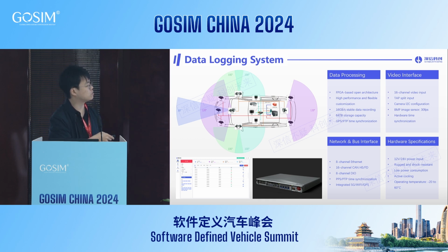For example, you need to trigger your cameras by aligning the camera exposure time with the LiDAR. The LiDAR is scanning in a rotating pattern, and once it reaches the view of any one of these cameras, you want that camera to expose and take a shot at the same time. So a very accurate timing signal needs to be provided by such a system.